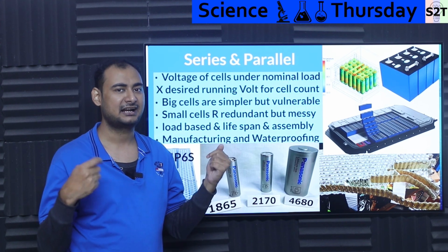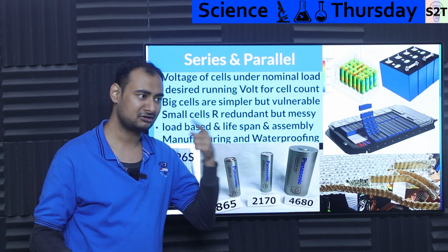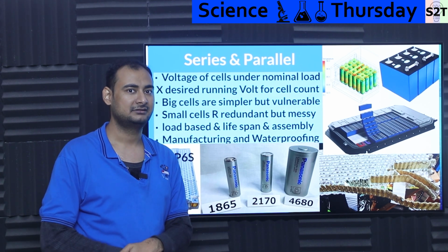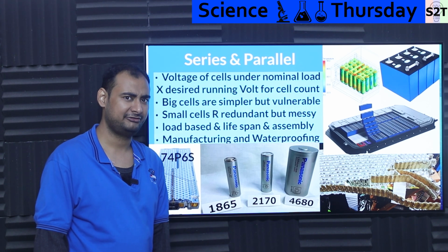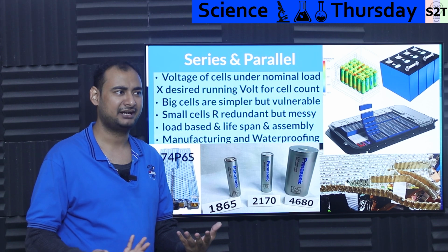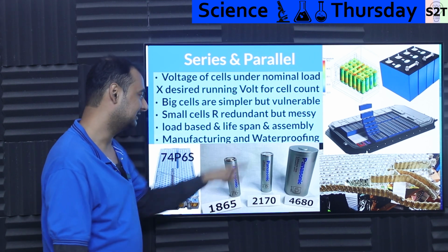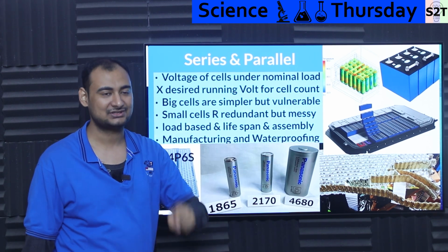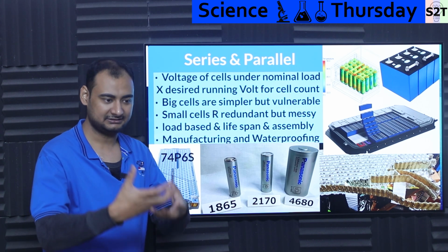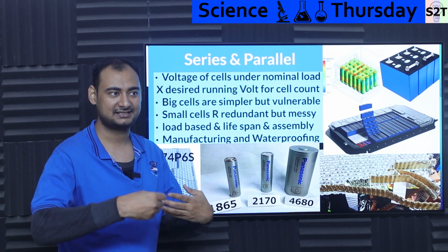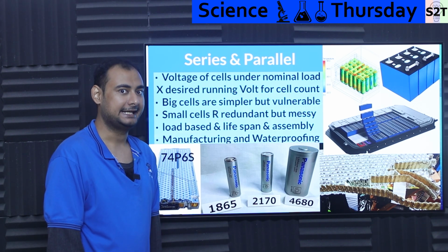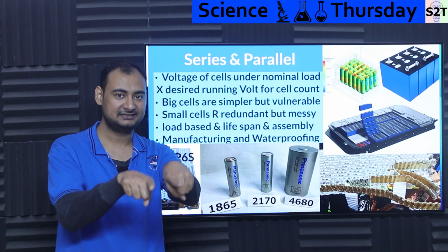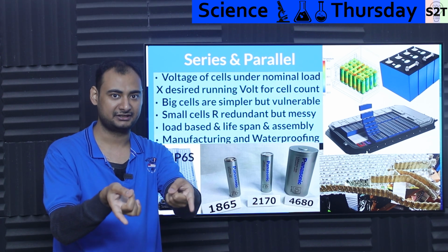Again, that's why things are randomly catching on fire after being flooded, not on day 1. But day 50 is like, huh. So again, that's my guess. Nothing else seems to fit why randomly it will catch on fire afterwards, other than the fact that waterproofing is failing because of that high voltage. Not that if you test it, it will be fine. It's just like test it underwater while it's fully charged. Yeah, even if the contactor is disconnected, that simply means that at the contactor you still have 800 volts or 1500 volts.